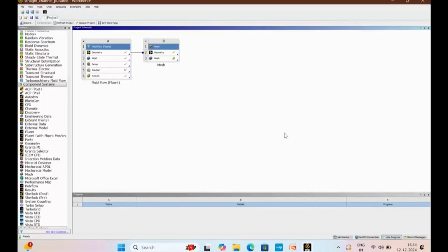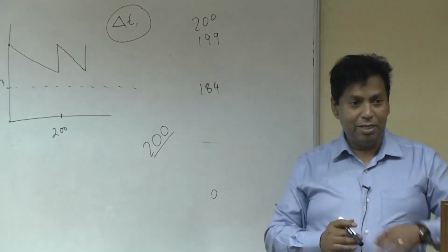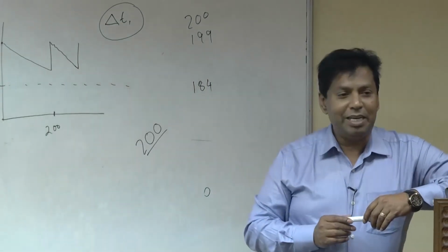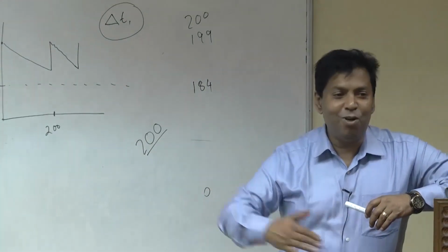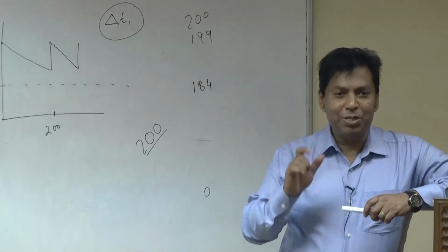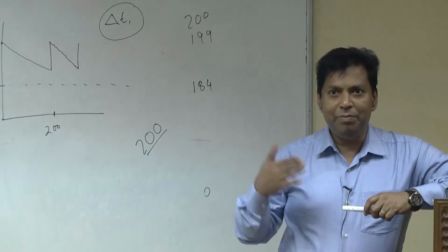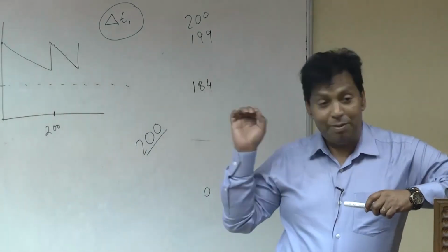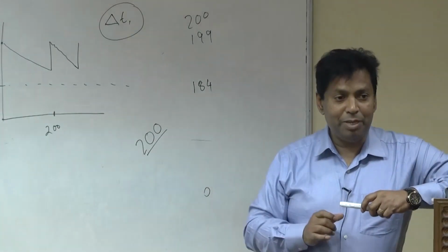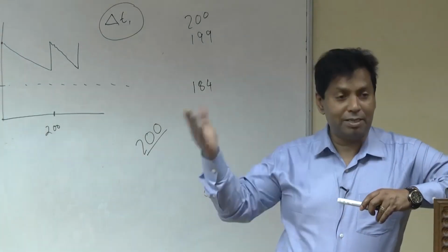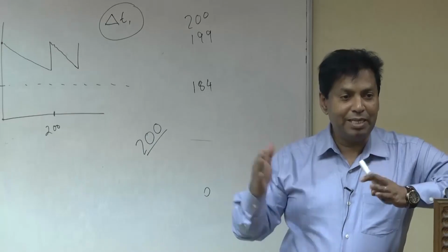Then you have to increase the maximum number of iterations. But there is another issue. Sometimes you cannot afford it. If every time step takes 500 iterations, it takes a long time to solve. So there are some issues. That time you have to do some debugging. Maybe it's your mesh issue, maybe your time step is very large. You have to make the time steps smaller, or adjust the relaxation factor. So a lot of things you have to think about at that time.